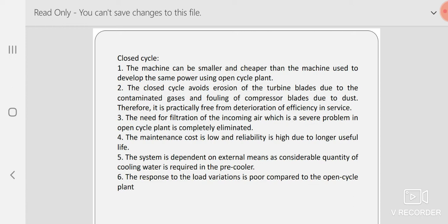Because you are not going to put a very high level of filter inside, because the higher level filter you put, the more is the suction cost in the compressor. Try to understand. Filter provides a resistance to air suction to compressor. And the more air suction required, the more power is required in the compressor.